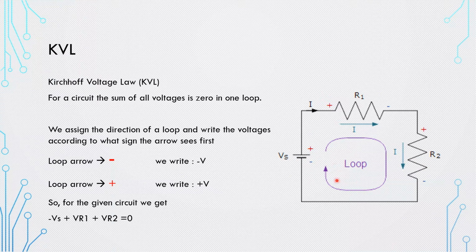This law says the voltage across each element in this loop, the sum of it, is going to equal 0, with the source that you have. So it doesn't talk only about the resistor, it also talks about voltage sources or any kind of element that you have in your circuit. So for a given circuit, the summation of the voltages in a loop is going to equal 0.